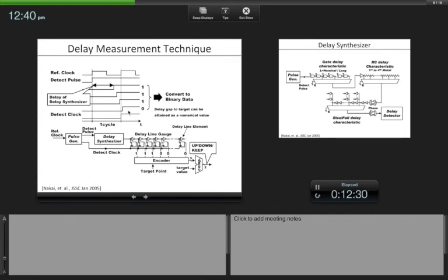So what you have done is, when the following clock edge comes, you are essentially taking a snapshot of how far the input edge has propagated in this, right? So for example, here the edge has propagated up to this point, the third point, right? This is one, this is one, this is one, this is not yet turned 1, it's in the process of turning to 1, it's still 0. So when the capture edge comes, it's capturing a 1, 1, 1, and then everything else is 0. So then you encode this, right?